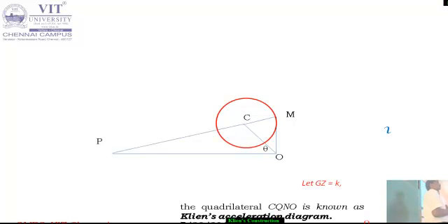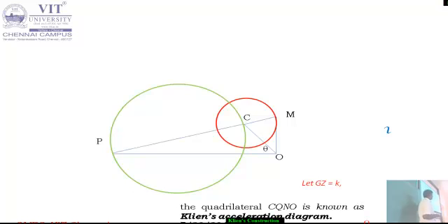We have to find out the inertia forces that are acting. We know the inertia force Fi acts opposite to the piston movement. So this Fi is here, this is Fp, and on the opposite side you have Fi. Fi is equal to m into A. That component you know, we have the formula to calculate that. Next, we have to consider the weight of the connecting rod. That weight will be acting on the center of gravity.